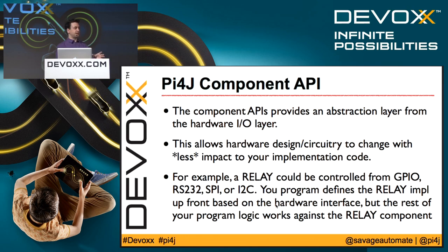And should your circuit design ever change, your program is insulated from that change, because where you configure those GPIO inputs is isolated to some initialization portion of your program.